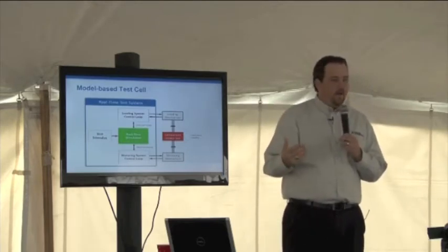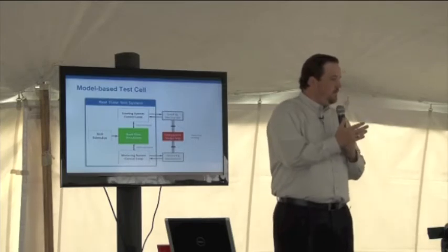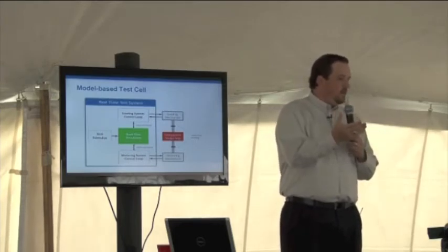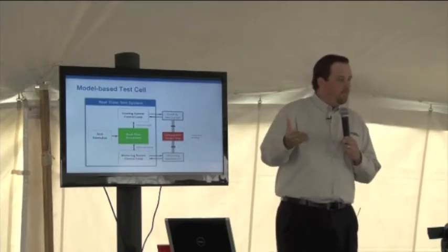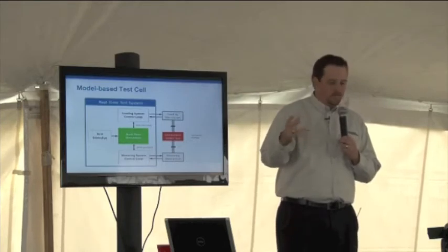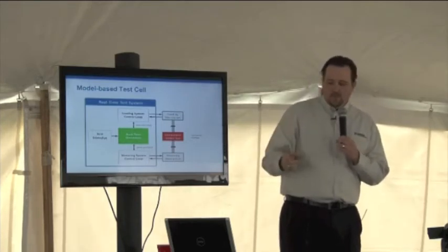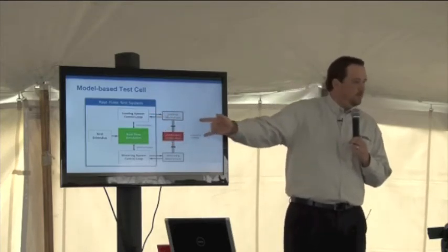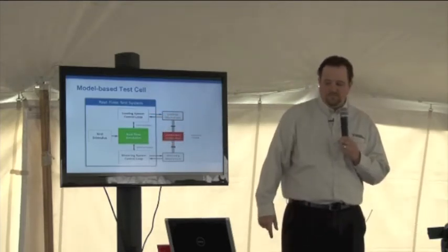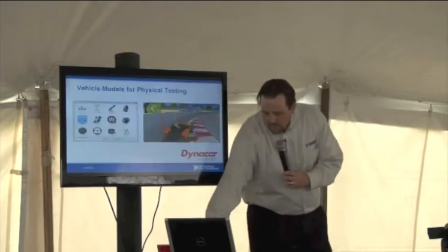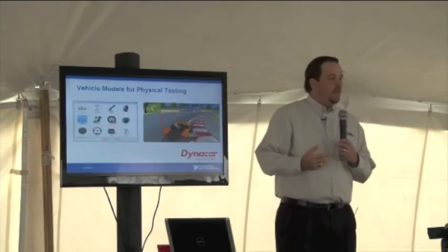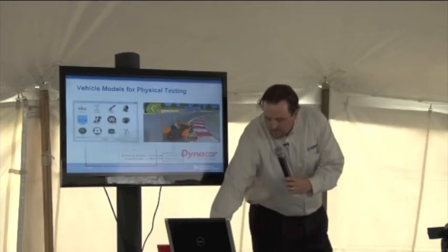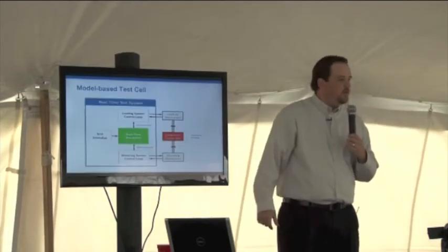And so you do that by now taking from the simulation the parameters or the signals that correspond to the load or the input power that would be made to that part where it's coupled to the vehicle. And then you feed those as set points into your control loops and drives and motors to actually do the mechanical simulation.